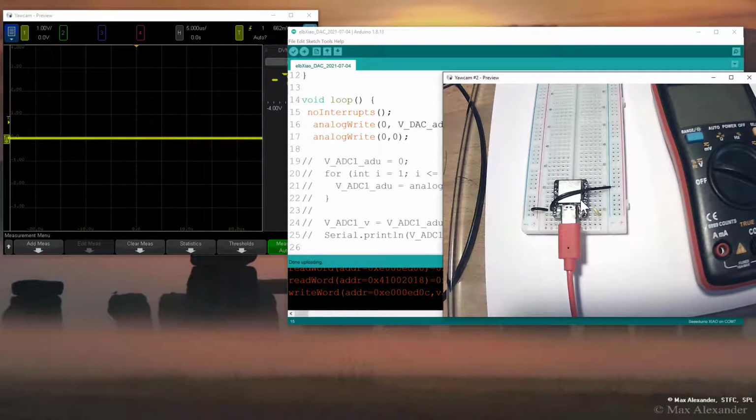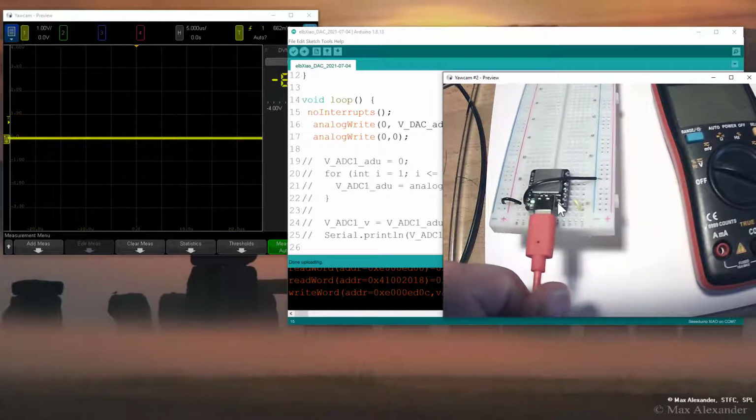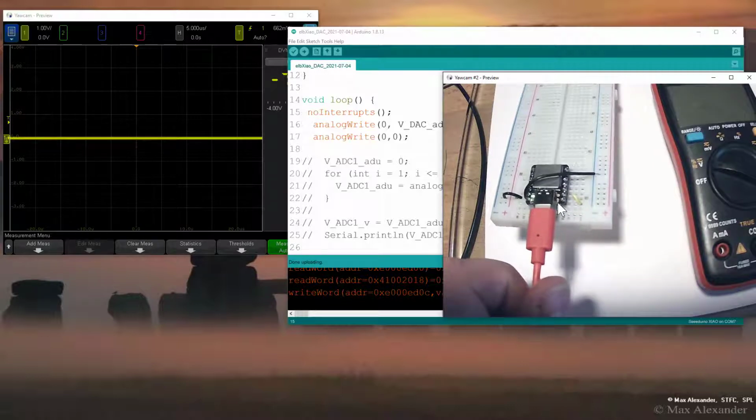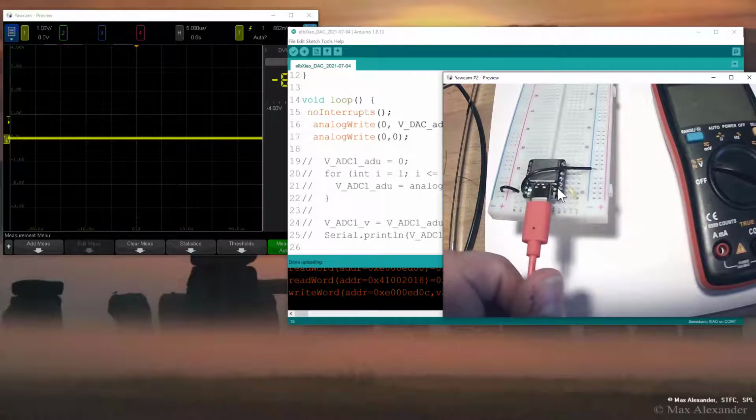And it's running the code, and I can't do anything about it. So what I have to do is set the Xiao module back to the factory state of the bootload. And to do that, remember I mentioned those reset pins, the pads. These are the two pads right here. I have to short them together twice in rapid succession, and that will reset the Xiao module to the factory